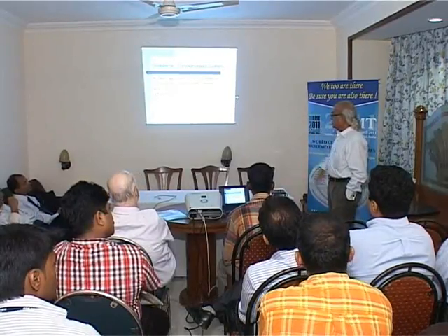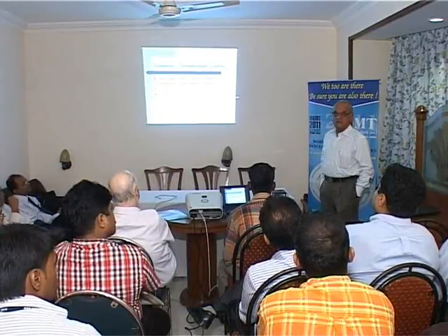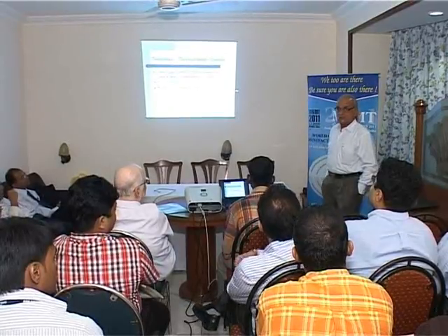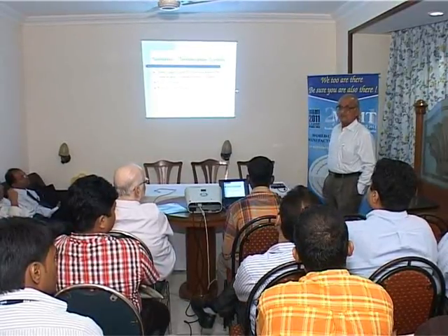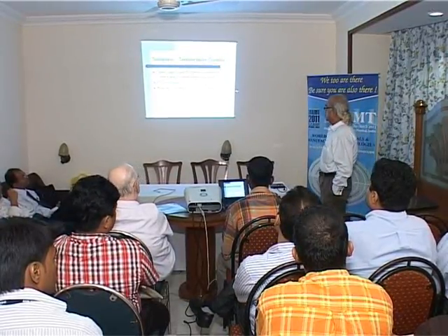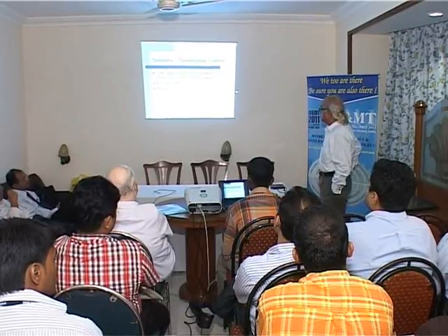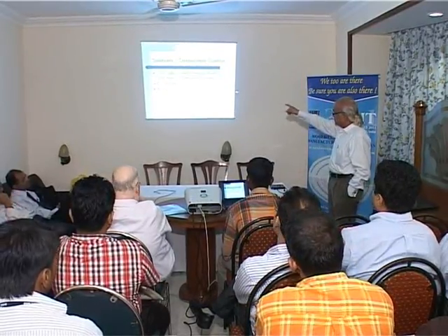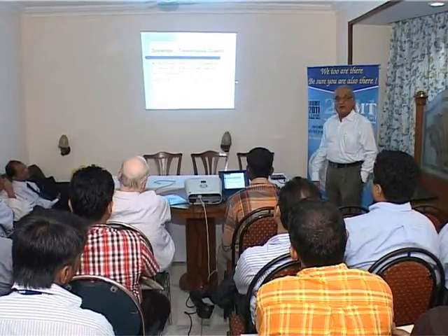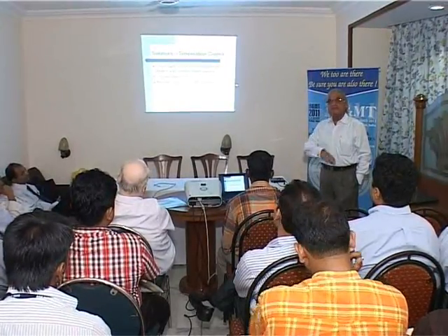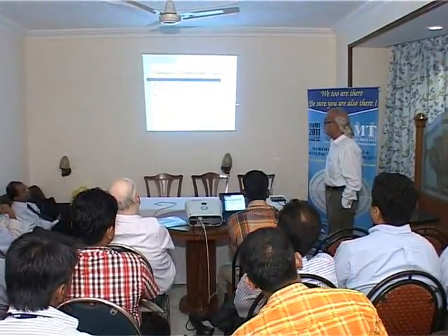And on-off controllers have no more relevance in the modern industry. We should go at least to PID controllers, if not programmable PID controllers. I think Kalpesh would talk more about it. And finally, this relocation of burners or heating elements, which I pointed out earlier. Next.